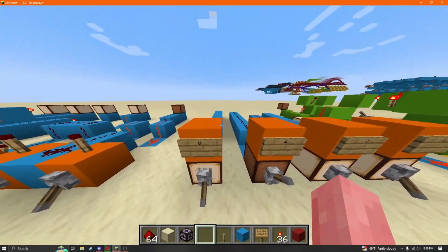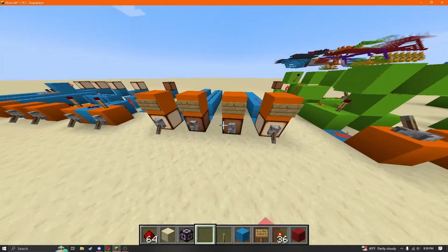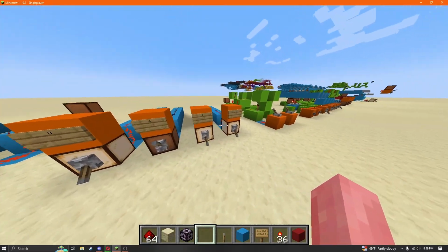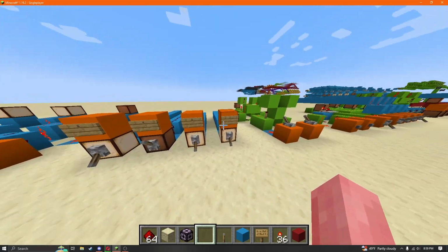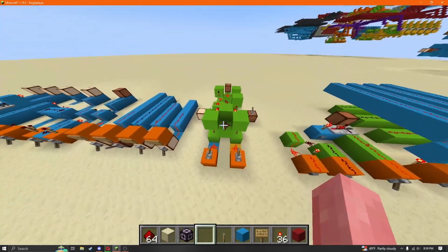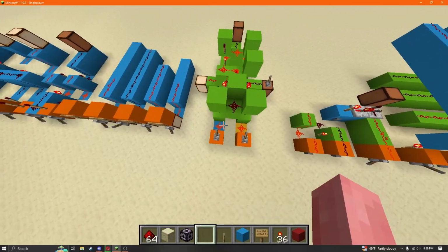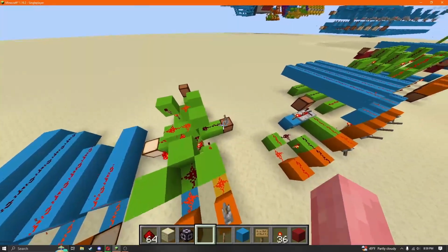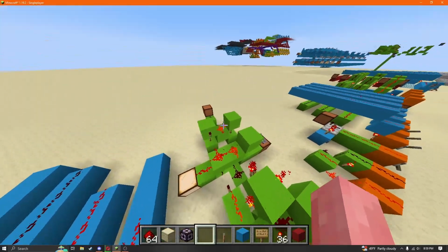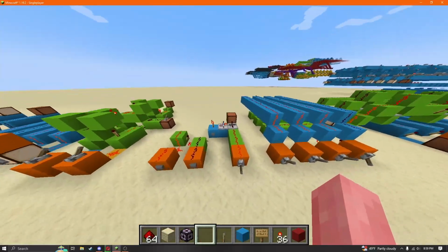In this project, we're going to be representing numbers with bits in binary. So let's go ahead and represent, this is going to be 8 plus 1 is 9, or let's go 11, which is actually going to be B in hexadecimal, which will come in handy later. This right here is a full adder. It takes in 2 bits and a carry bit, and it outputs the sum and the carry out. We'll go over this later when we get to that.